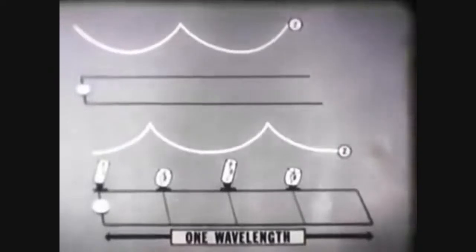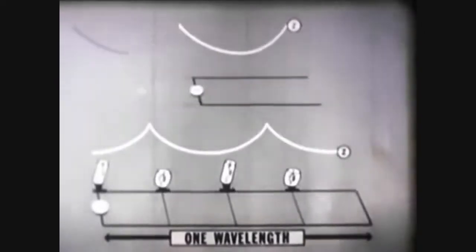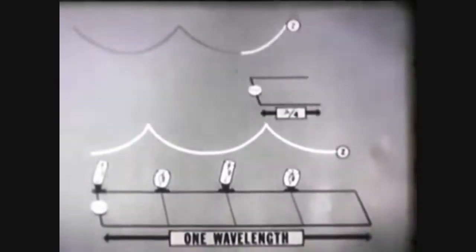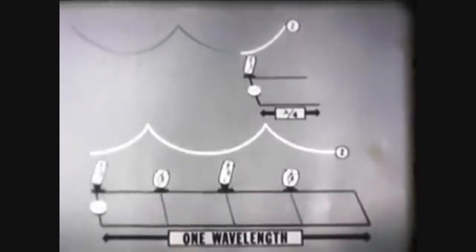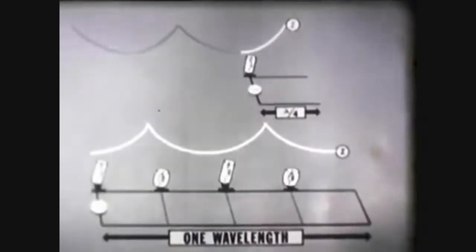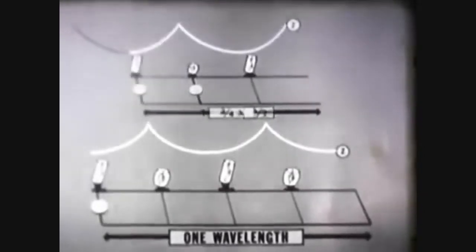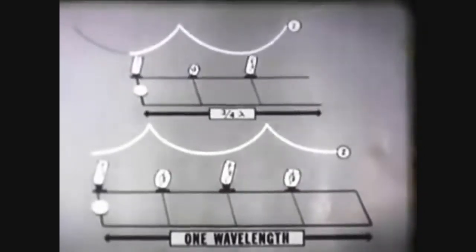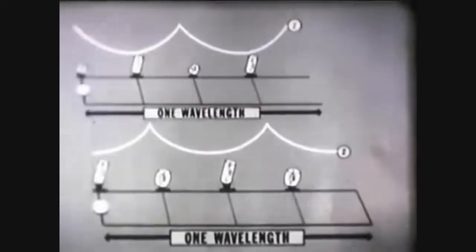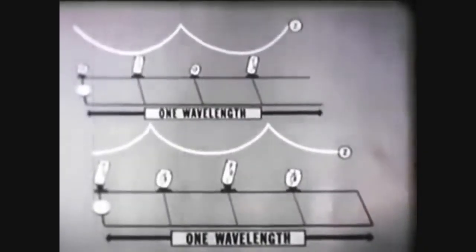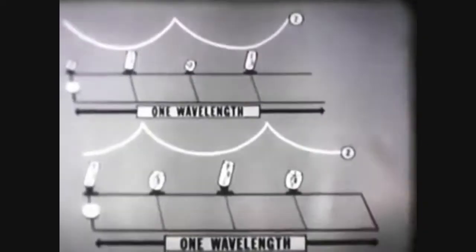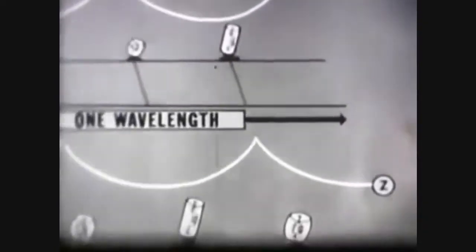The behavior of our open line can be investigated in the same manner. At the 1/4 wavelength point, the generator sees a condition of minimum impedance. This circuit can then be considered a series resonant circuit. Each time a 1/4 wavelength is added to the circuit, the condition changes. Thus, open and closed end lines can be used as parallel or series resonant circuits according to the length of line used. Because of this facility, they are known as resonant lines or tuned lines.